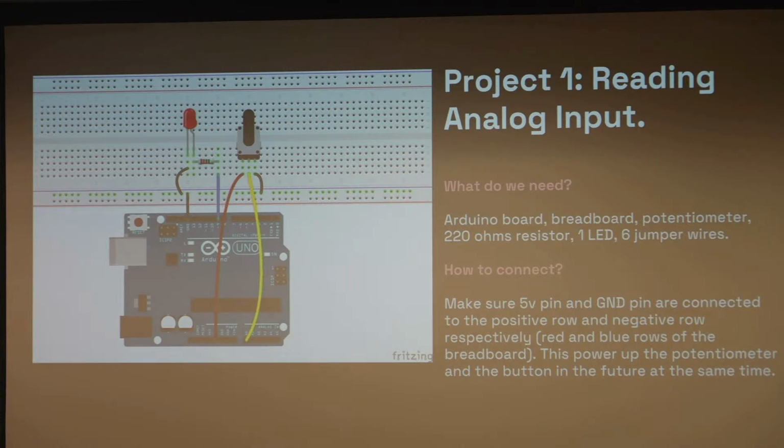Remember that for the breadboard, the energy flows column-wise. So for example, if you connect this red wire, it's going to fit only this column, right? Yes. Or the leg, which is the pins. So I think here, for example, it's not hitting the pin. The black one? All of them, actually. These three. Yeah, so you might just move it one column to the left.